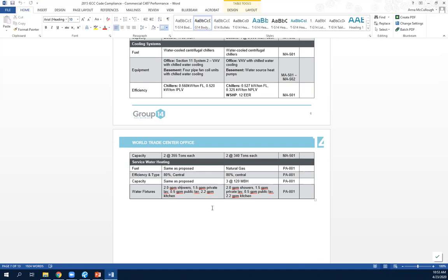It really depends on who the occupants of the building are and why that building is being designed the way that it is. For a rec center, for example, or a school, we don't see them increasing their glazing, their window to wall ratio, I guess I should say, above what's prescribed. But they often say that they don't want to comply with the prescriptive wall assembly.